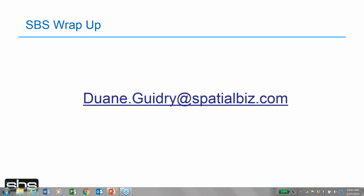Thanks, Steve. Basically, we have the same thing at the AutoCAD electrical end. If you're doing brownfield and you don't have a model, we have a tool that basically mimics what Steve just described for the Inventor part. Either one, they both generate the same data, and then the AutoCAD electrical SBS tool set takes that data and generates the cable schedule and does the voltage drop checks and does the conduit fill check. Oh, okay. Thank you very much.